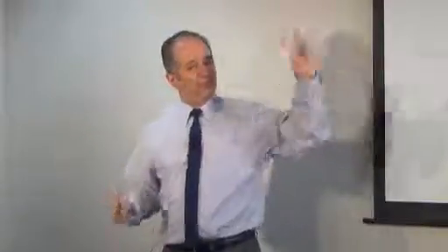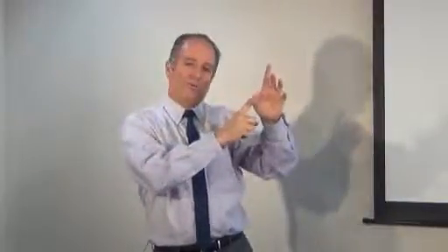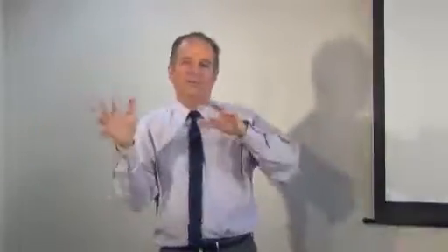They'll do it at such and such an hour, and they take the line out so they can do the maintenance. Meanwhile, they're finding out that with that line out, this is the next worst contingency. If that happens, we'd better start unloading that line a little bit, because if that goes to overload because of this line trip, we're in trouble. So you have this analysis going on, and you get to do those kinds of things on a simulator.